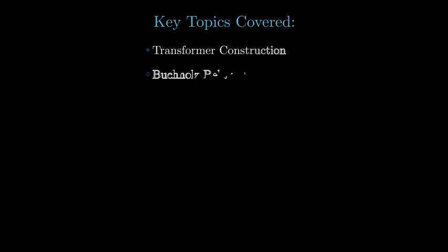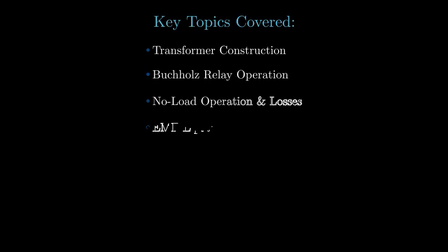And that brings us to the end of our summative assessment walkthrough. We've covered a wide range of electrotechnics N4 topics related to transformers, including construction, safety mechanisms like the Buchholz relay, no-load operation, various losses, and important calculations using the EMF equation. By understanding these concepts and practicing the formulas, you'll be well on your way to mastering this crucial section of